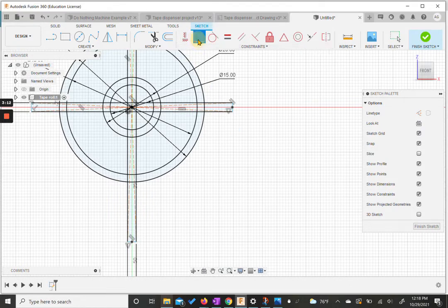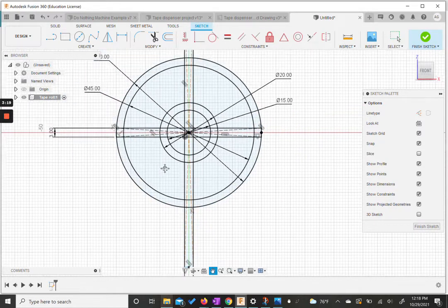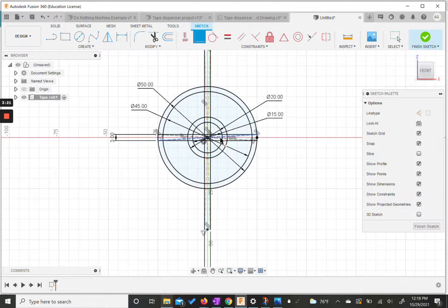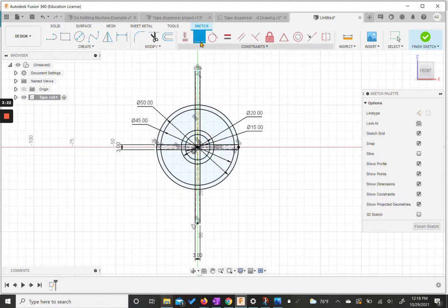All right, then I'm going to come up to our coincident constraint and choose my little point and the outer circle. If you notice, that snapped it on both sides. Here, let me zoom out to show the other one. We have the coincident constraint still on our cursor. I'm going to click the dot that I had made, and I'm going to click the outer circle, and now this snaps our rectangles in all the way to that outer circle.